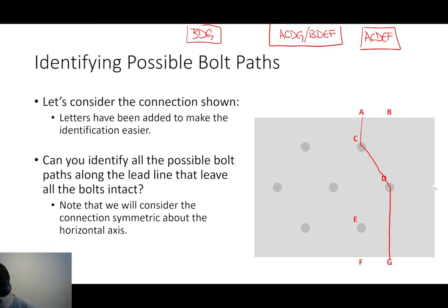So why would the plate fail in this diagonal fashion? If you're yanking on this in tension, it's wanting to fail perpendicularly. So all of the lines are going to want to be vertical unless they're fracturing from bolt to bolt, in which case you're going to have a straight line between those bolts, because that's the least distance between those bolts.